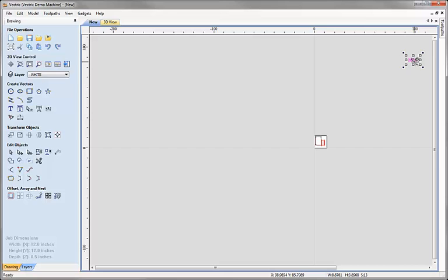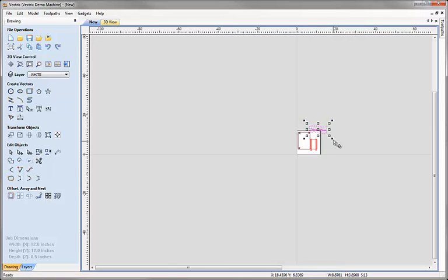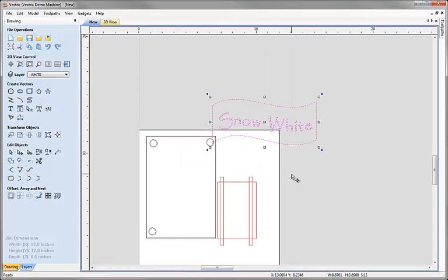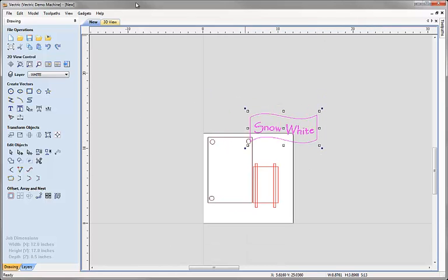The reason that it's imported up there is it has done exactly the same thing as the first file import. It's maintained the original position of the vector geometry as it was saved. So be aware that sometimes when you receive files from third parties, you don't really know the exact position of that geometry in real units, and so it may well be way off your initial design if you try and import it through this route where you've laid out the design first.